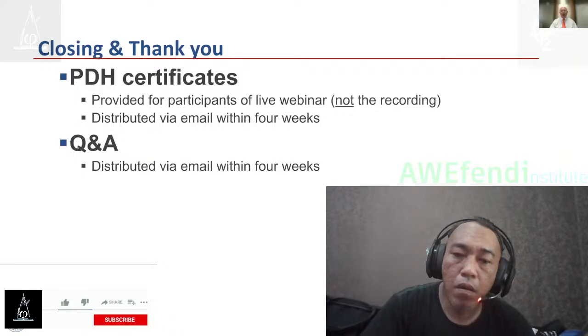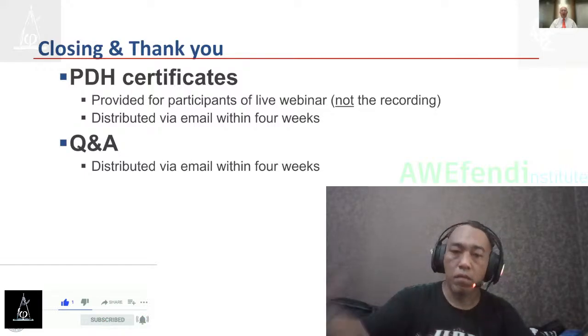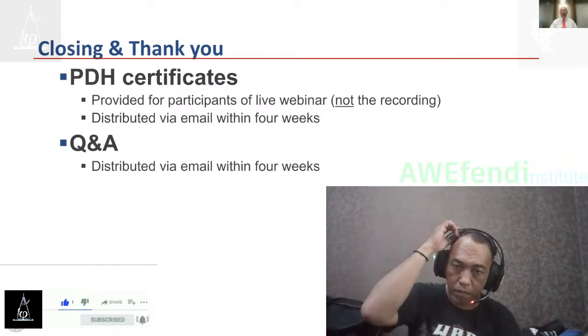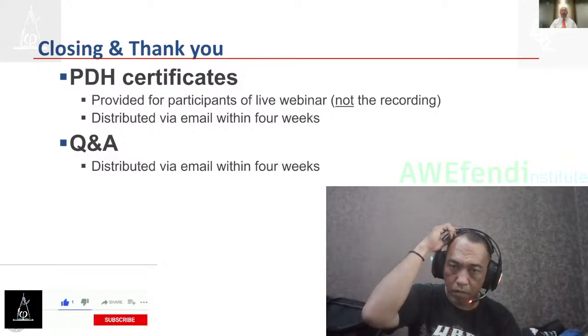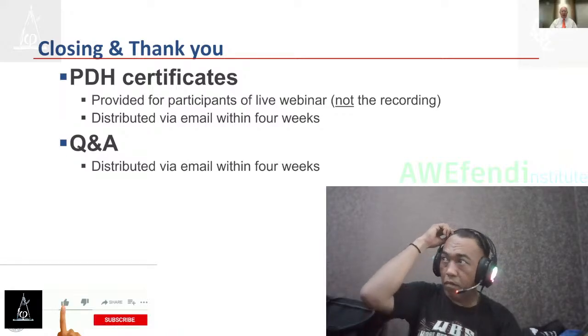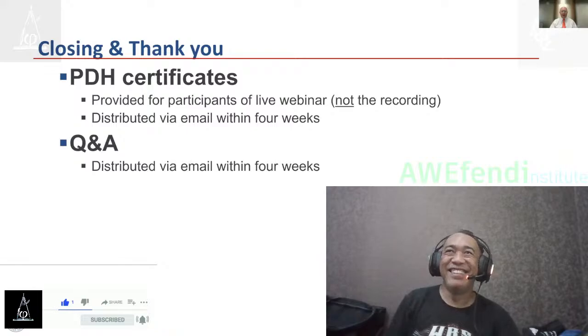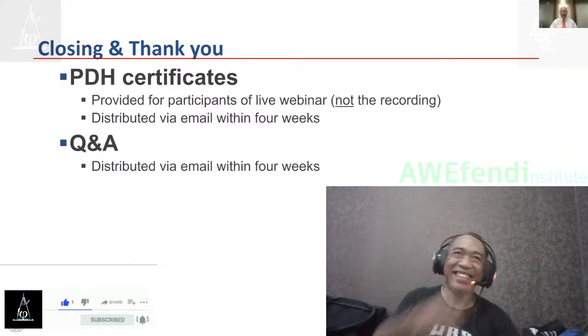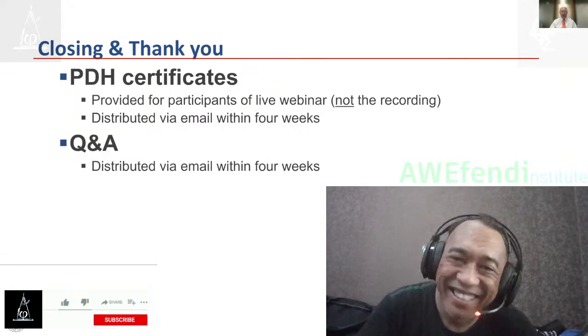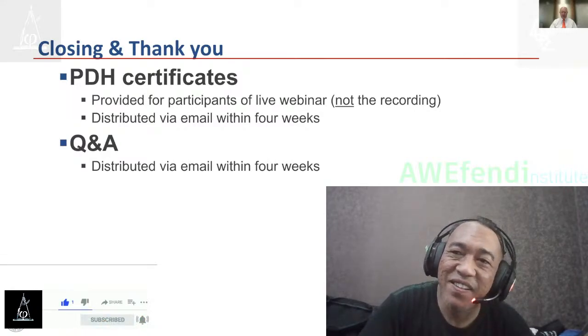But probably story weakness or story flexibility. So weak story or soft story, perhaps those are most susceptible to some duration effects. The strong column, weak beam rule is important. If you have lots of cycles of inelastic response at a joint, it would tend to deteriorate. And so any of those that we identified as collapse concerns may well be worsened by long duration and multiple cycles.